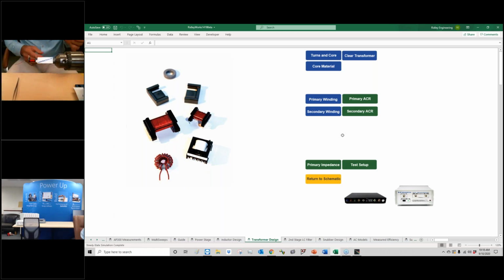What do you need next? We've got some tape, yellow tape, we call that. It's special tape. It's not something you can go buy at Walmart. I don't know who sells this stuff these days. I get it from electrical insulation supply. I don't know if DigiKey has it or Mouser. You put your tape down. It's very thin, but it's good for several thousand volts.